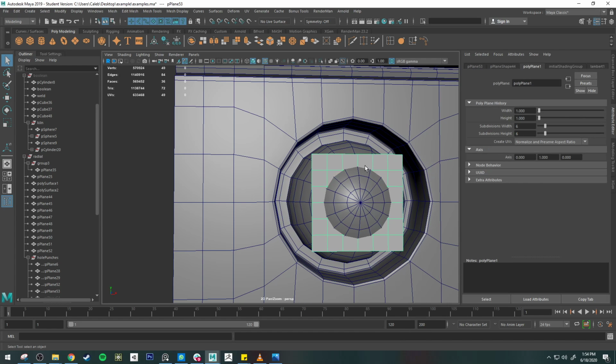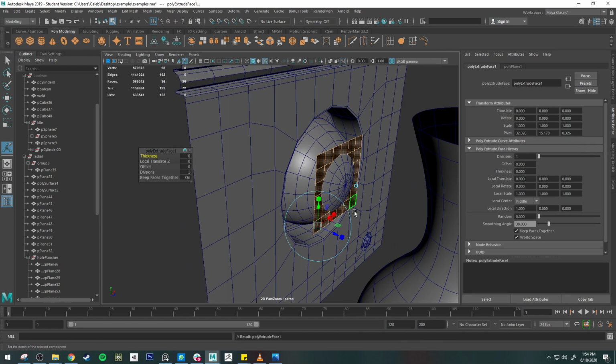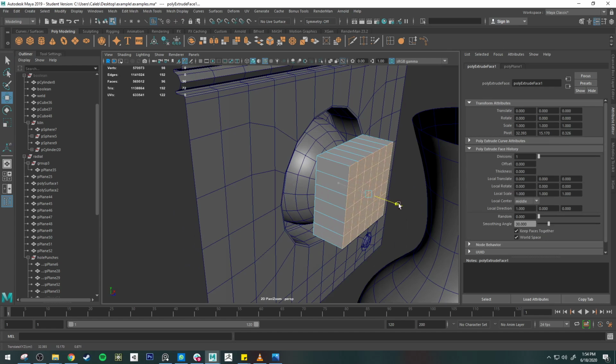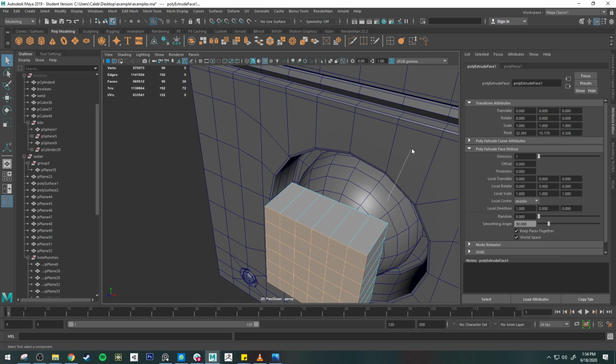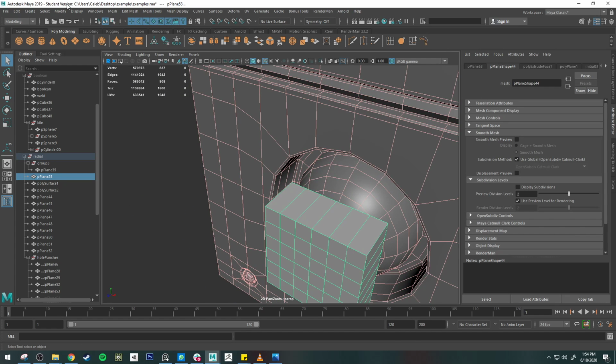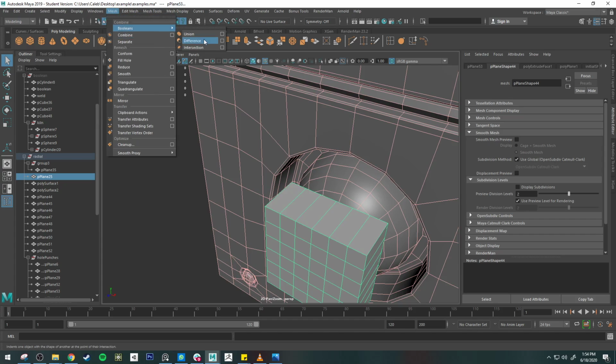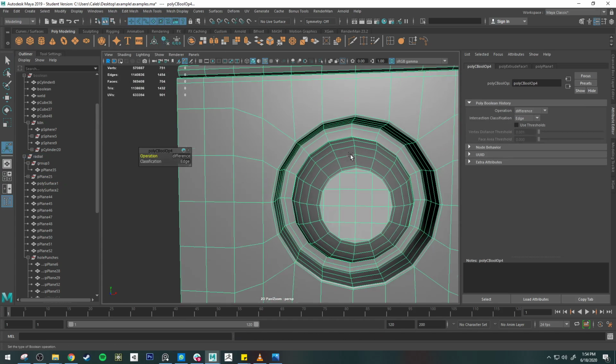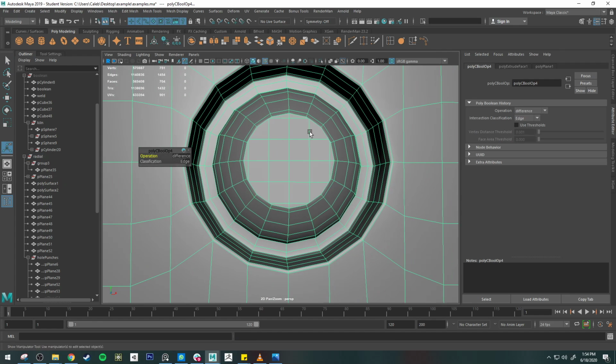So let me go ahead and extrude this first, just so I have a volume to cut or subtract from the other object, right? So what I can do is I can grab this, and then go mesh Boolean difference, and I have that. And so I mean, this is okay. This isn't going to be a huge problem. The nice thing is I have the right poly count.